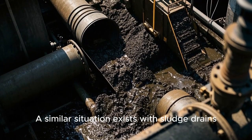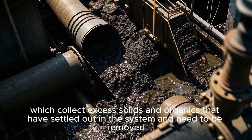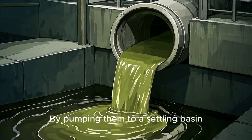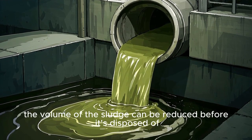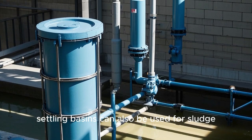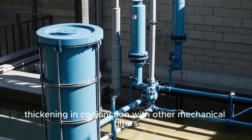A similar situation exists with sludge drains, which collect excess solids and organics that have settled out in the system and need to be removed. By pumping them to a settling basin, the volume of the sludge can be reduced before it's disposed of. In addition to these uses, settling basins can also be used for sludge thickening in conjunction with other mechanical filters.